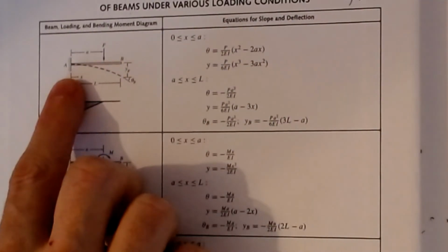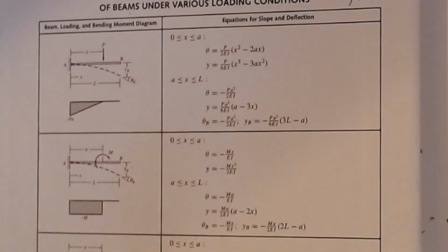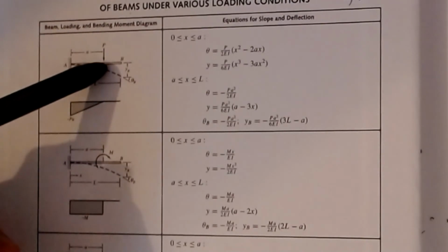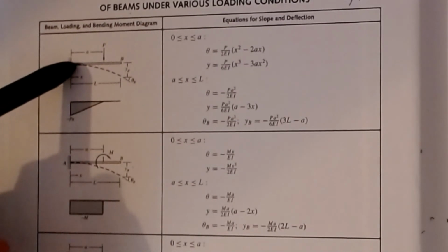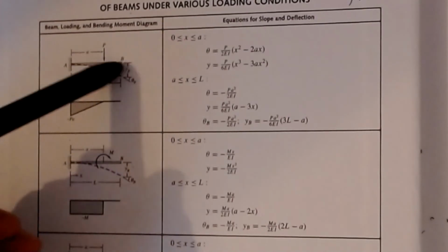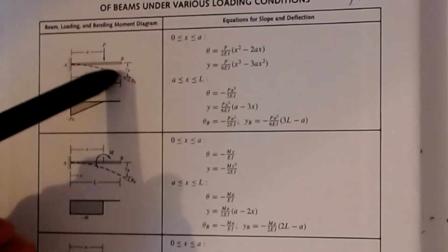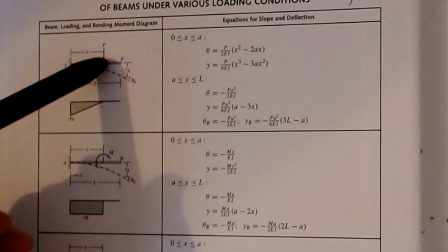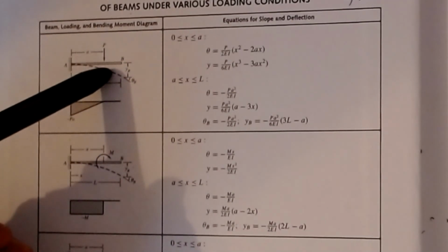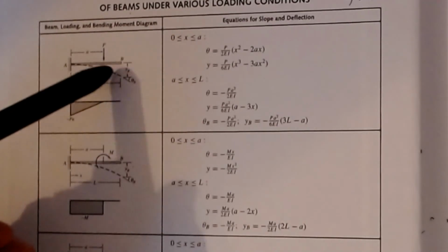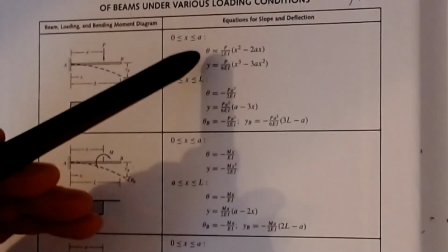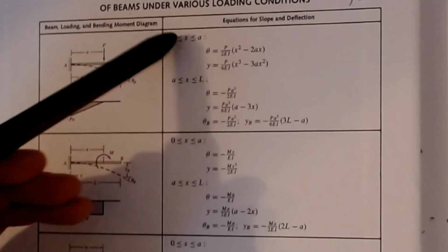In this particular case, because of the point load being here, there would be 2 different regions. There's a region to the left of the load in which the beam is flexing, and then there's a region beyond the load in which the beam is just extending down further. In fact, that extension that's happening here is because of the slope change at the location of the load. Okay, and then there's no flexing beyond that. There's no moment in this piece that's outside of this. But here are the equations for the slope and the displacement for each of those cases.